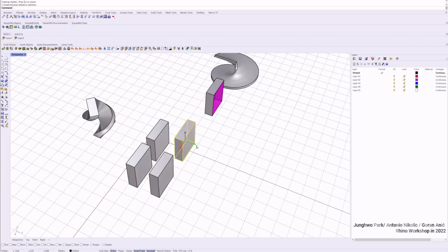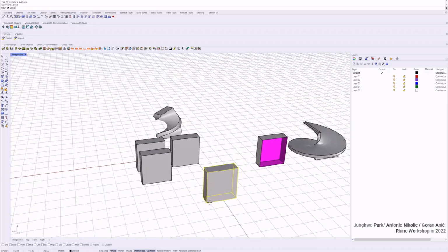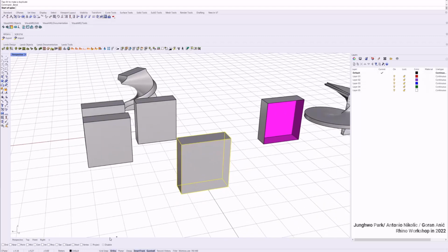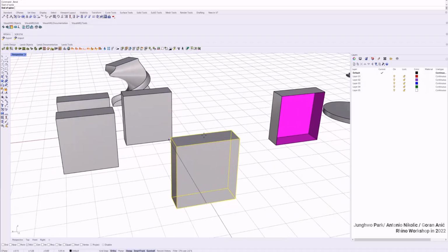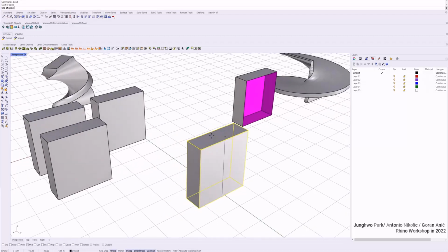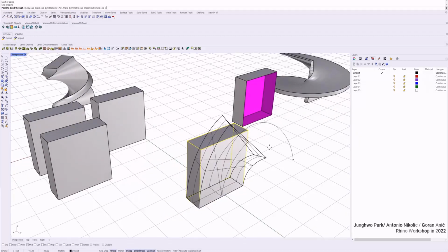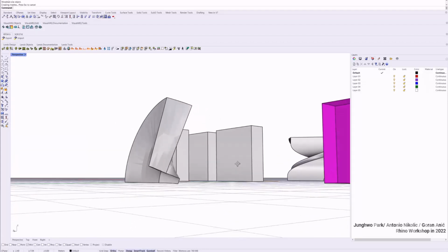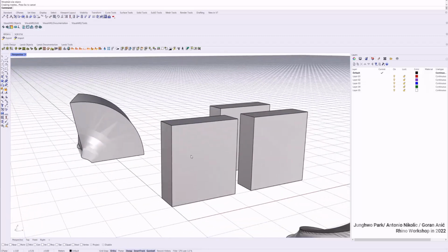It works. And another one, you can also bend it. So you can draw the spine where you want to bend. I'm gonna use middle again. This time I'm gonna select another part like an edge. So this is our spine to bend, and you can bend it however you like. So that's the bent geometry. I'll try again.